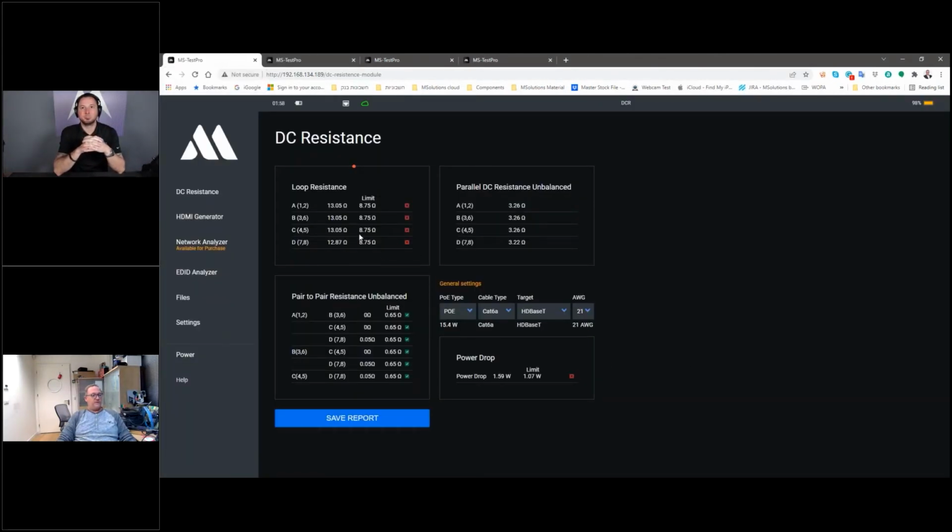I've seen a lot of cable which are actually copper coated aluminum and copper coated steel, and I'm saying that a lot of times. It means that the core of the wire is either aluminum or steel, and it is covered with copper. Those cables come with very high resistance. They will be balanced on the testing for the IEEE, but they will fail because of the high resistance. So this is the information for LAN and HDBaseT.